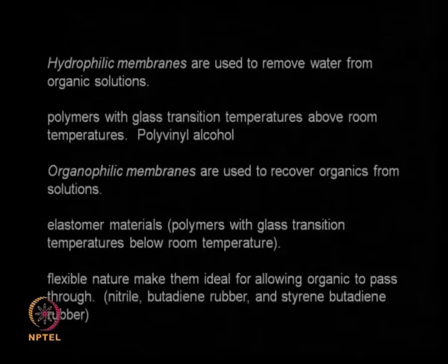Now membranes, let us look at membranes. So as I said, you have two types of membranes, hydrophilic membranes, and organophilic or lipophilic membranes, or hydrophobic membranes. Hydrophilic membranes are very good for removing water from organic solutions. That means the amount of water present in a mixture of organic solvent is very little.